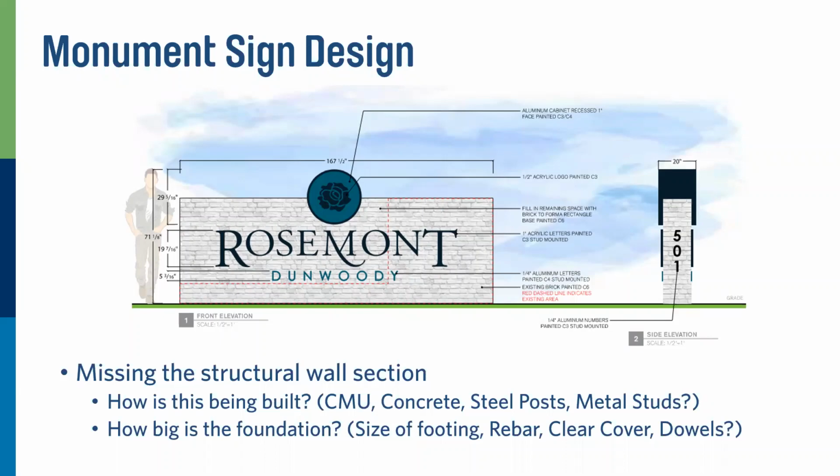You're missing all the structural wall sections, like how is this being built? Is this CMU? Is it steel? Is this metal studs? What about the foundation? What is it sitting on? We have to have all that information, again, because all of that has to be designed for that wind speed.